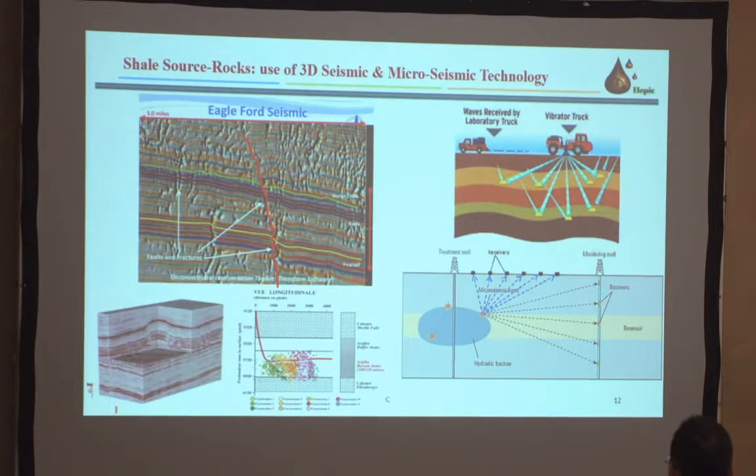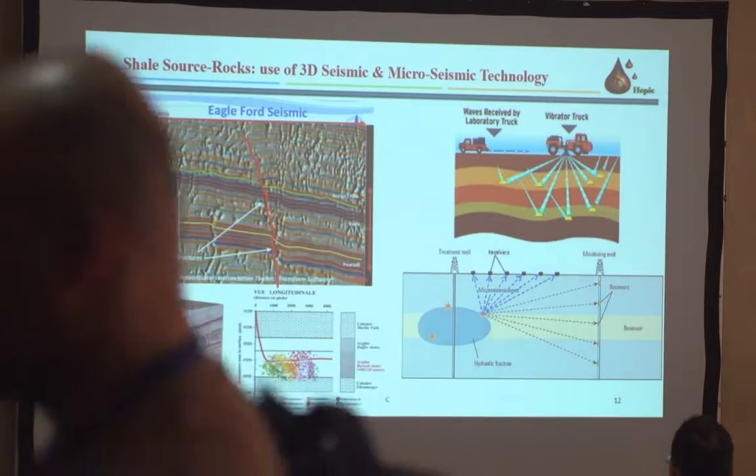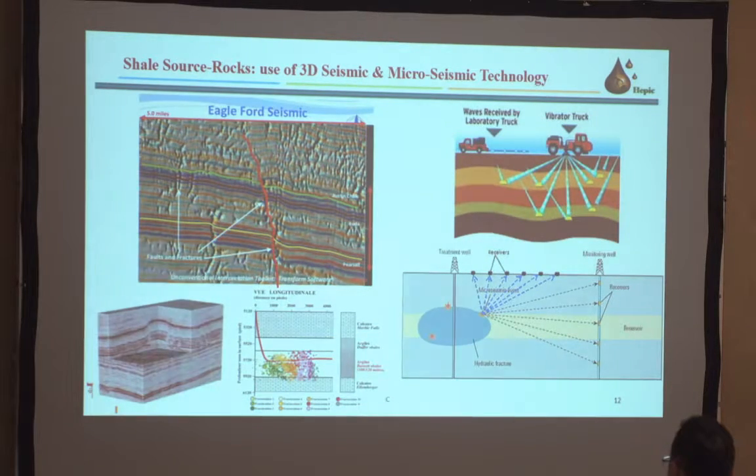This is a schematic cross-section where you can see the location of the well path, the horizontal section, and color-coded the different fractures which have been undertaken. This area has not been fractured yet, but you can see that your fractures are well positioned within the main shale and did not propagate to the surface as many fear, and you can see if you have properly fractured your zone.